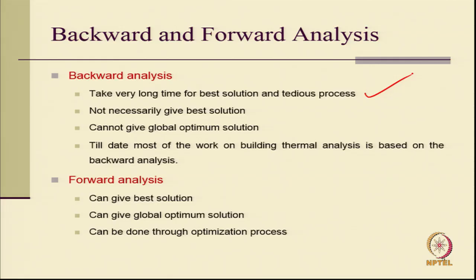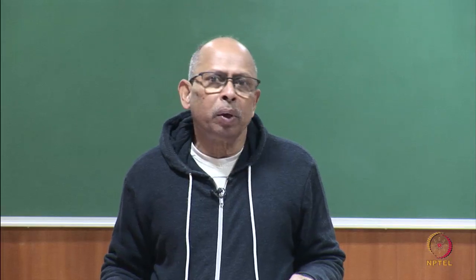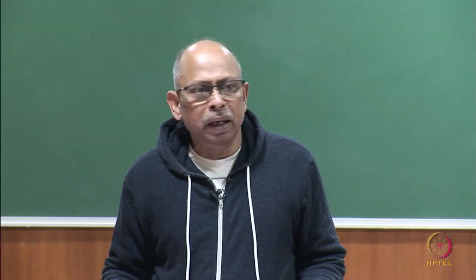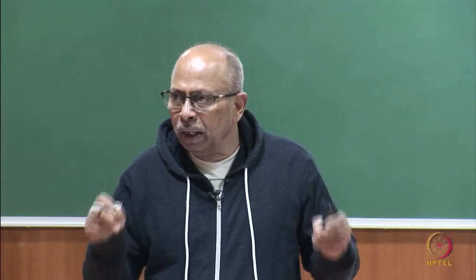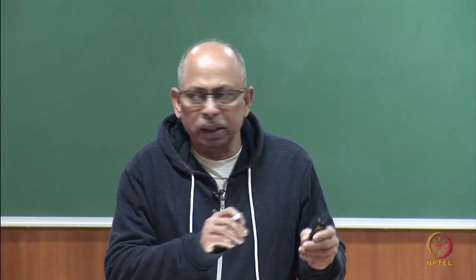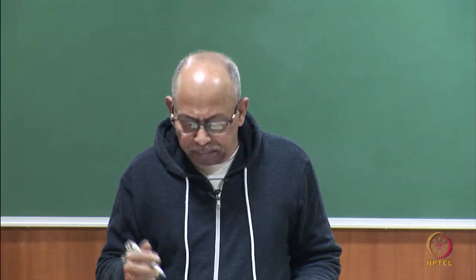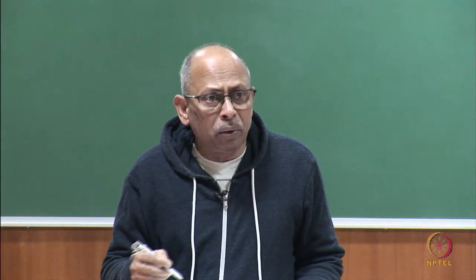Backward analysis takes a very long time, is a tedious process, and does not necessarily give the best solution; it cannot give the global optimal solution obviously. Till date, most work of building thermal analysis has been based on backward analysis. There are several tools or guidelines available from a long time, what you call prescriptive guidelines. There is something called Mahoney's chart, something of this kind. So, you have tables: if this is your climatic condition, use this, that sort of thing. These are all part of backward analysis.